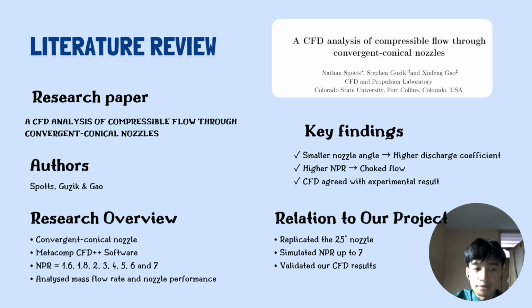analyzing compressible nozzle flow. Our project is based on this research, and we replicated the 15 degrees convergent conical nozzle and performed simulation up to the NPR that I stated just now, and compared our results with the published findings to validate our CFD model.